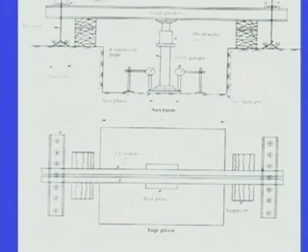In this particular figure you can see that there is an excavation of 5 times the width of the test plate. So, this is the test plate and 5 times the width. The depth of the foundation is up to the proposed level of foundation.